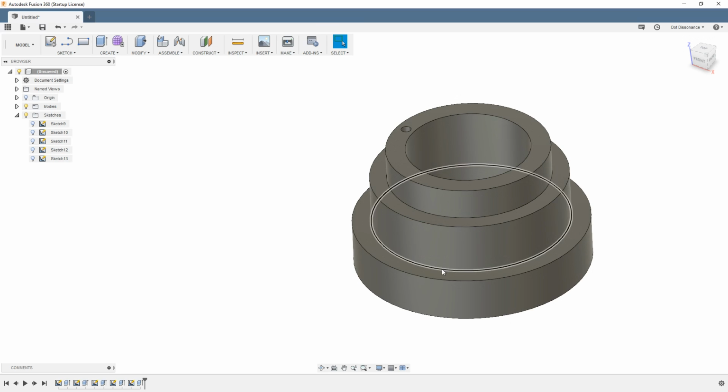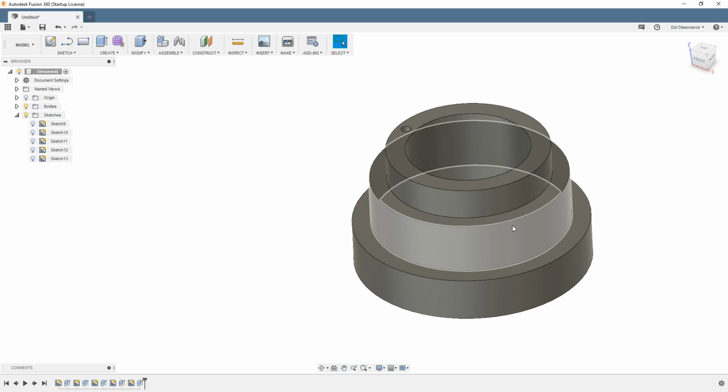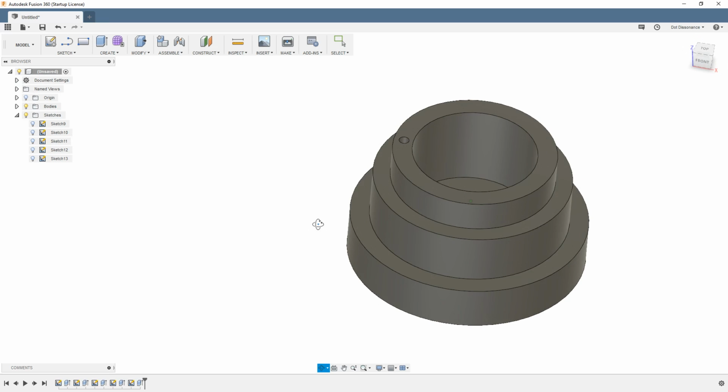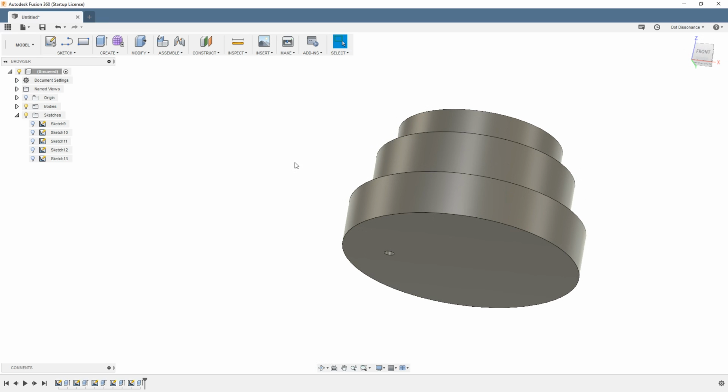If I come along later down the road, because I'm making multiples of these parts, and the customer says, hey, I'd like to have one a little bit taller, you make this extrude right here a little bit taller, well, now suddenly this hole, if it was done by a distance, will not be going all the way through anymore. It would just be, let's say, 50, right? But if I say through all, whatever the lingo is in SolidWorks or other programs, you get the point. If I say that it goes through all, then it will always go through all.